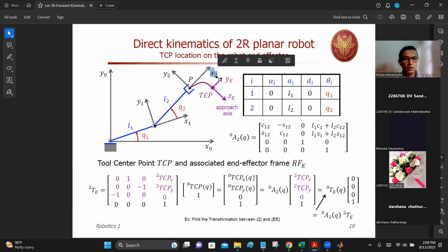So this coordinate mapping, x to y, z to x like that, is already done in the rotation part. So therefore, you don't have to worry about it. You write down the displacements with respect to its own coordinate frame, and then the transformation will adjust it to the other reference coordinate axis.